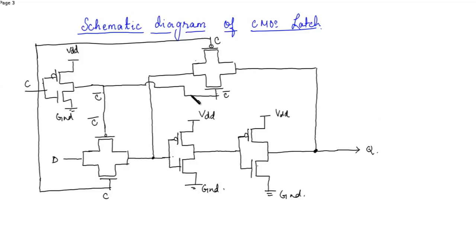So a total of 16 transistors will be used if we use 4 2-input NAND gates. If we design using transmission gates, then this is reduced to 8 transistors, which is done by using 2 transmission gates and 2 inverters.